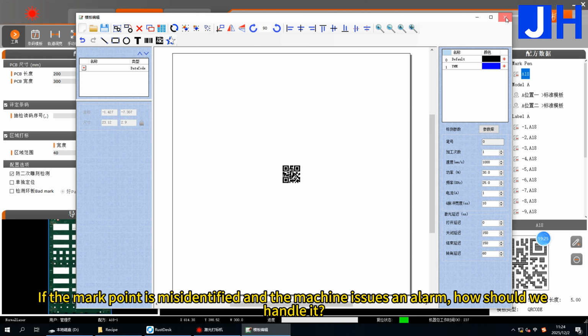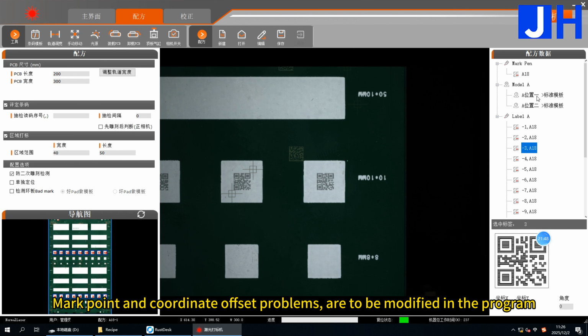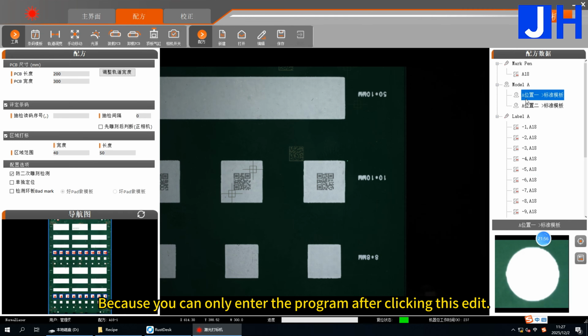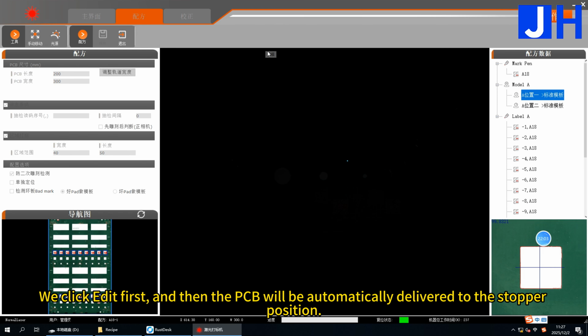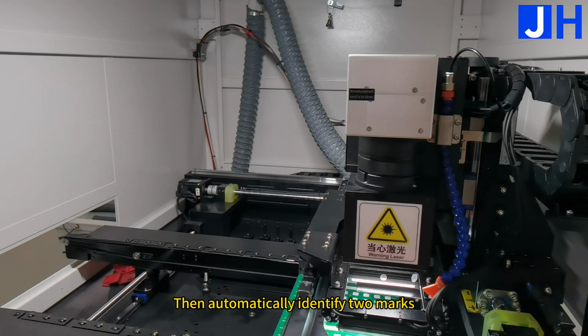If the marking point is misidentified and the machine issues an alarm, how should we handle it? Mark point and coordinate offset problems are to be modified in the program. We're going to click Edit and then modify the content, because you can only enter the program after clicking this edit. We click Edit first, and then the PCB will be automatically delivered to the stopper position. Then it automatically identifies the marks.